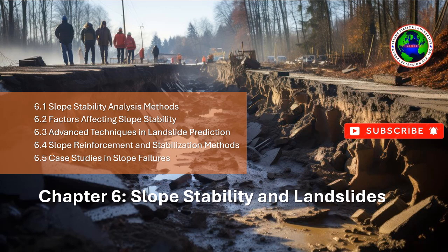LiDAR, light detection and ranging. LiDAR technology provides detailed, high-resolution topographic data of slopes, which can be used to create 3D models of the terrain. By comparing changes in the topography over time, LiDAR can detect subtle surface movements that may indicate slope instability.